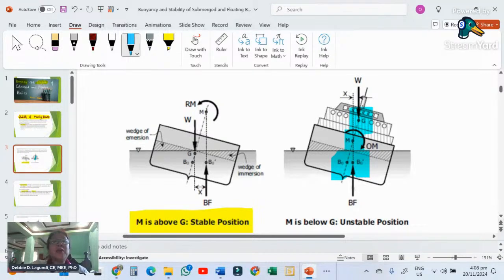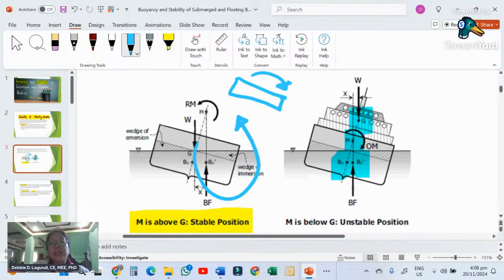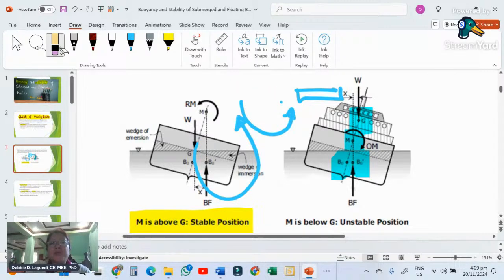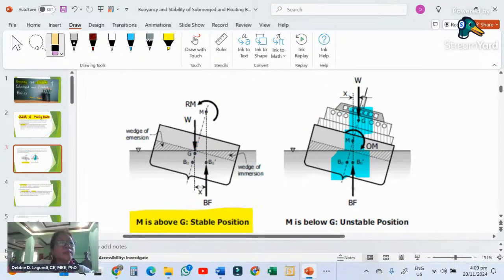However, if the weight will make a moment to the metacenter in the right direction, counteracting the body that is being tilted, then look, there is a moment that causes the body to tilt this way, but because of the weight having a moment to its metacenter, this becomes horizontal after a while. Why? Because it counteracts whatever is causing the tilting of the body.